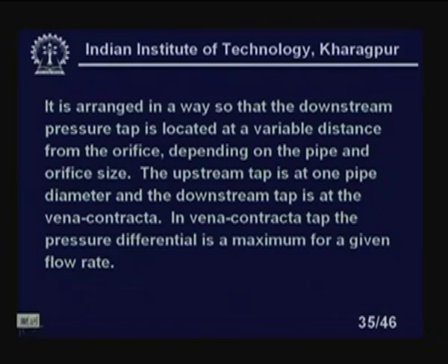In the vena contracta tap, the pressure differential is a maximum for a given flow rate. This is important. Okay. At the vena contracta tap, the pressure differential is maximum for a given flow rate. As I told you repeatedly, what is the advantage of having a large pressure differential?